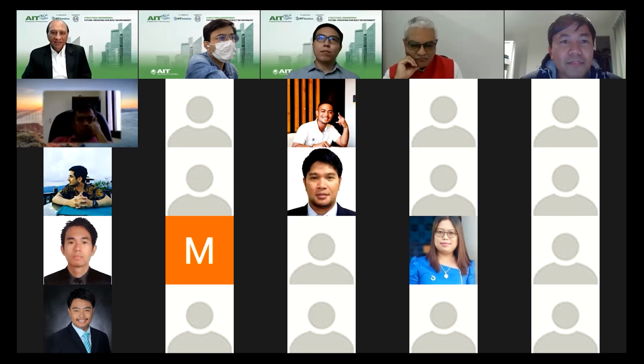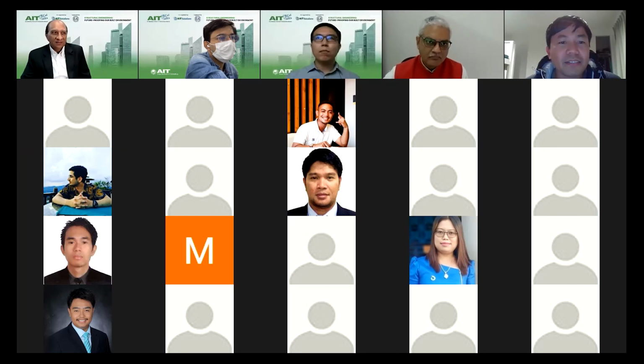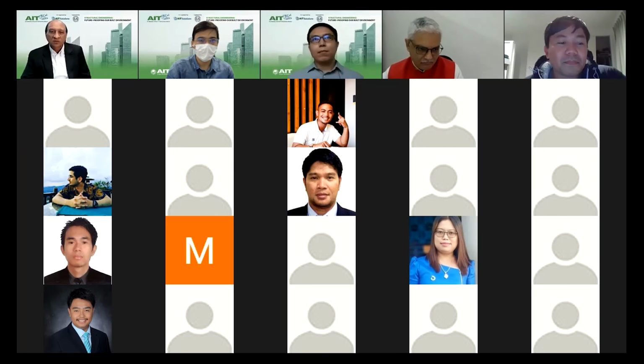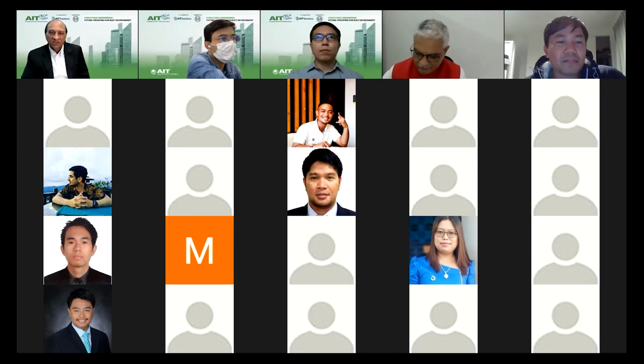Yeah, absolutely. There are several guidelines, but the most common is the Tall Buildings Initiative, TBI. There are also guidelines from ASCE, CTBUH and many other organizations. Maybe Mr. Ong can share the list later. We have a whole list of guidelines that tell you how to start the process. TBI is a good way to start, because it also gives you good justification why PBD should be done.